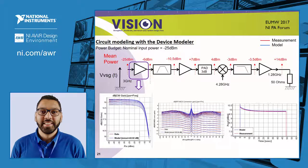Now the last graph is used to validate the model on a different signal. It shows the comparison of the measurement and the model on a pulse at 1 dB compression gain and confirms the good representation of the memory effect.